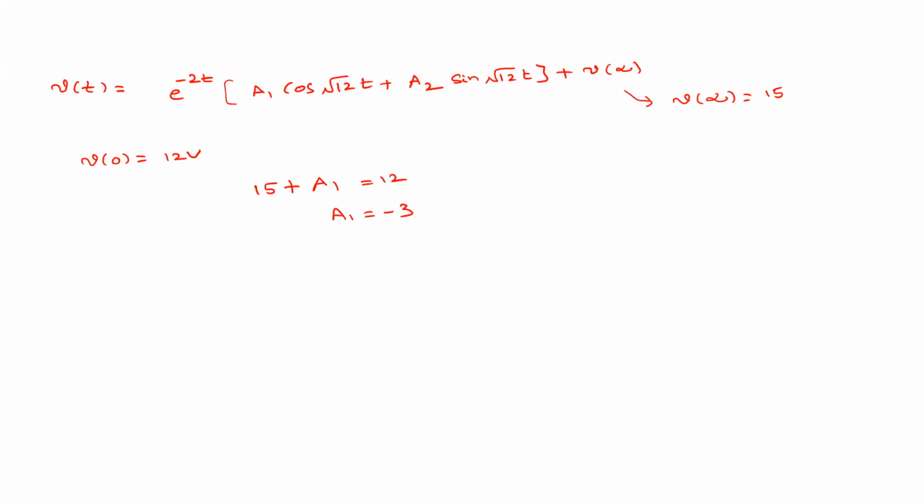Right. So now this is one initial condition. What is the other initial condition you require? I of 0 is 0. Here we are calculating the voltage, so dV of 0 by dt you require. Ultimately you are finding the response for V of t, so you require two initial conditions, V of 0 and dV of 0 by dt.